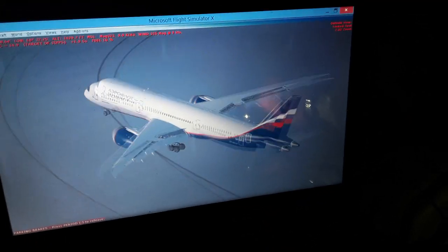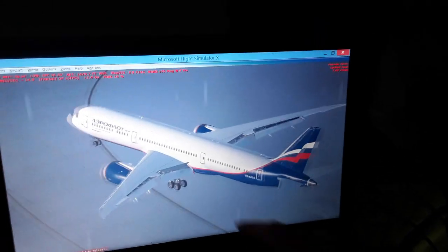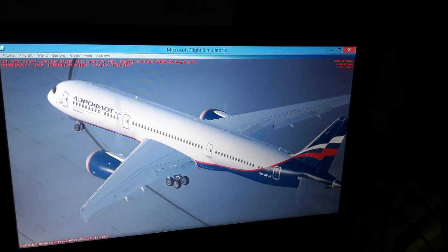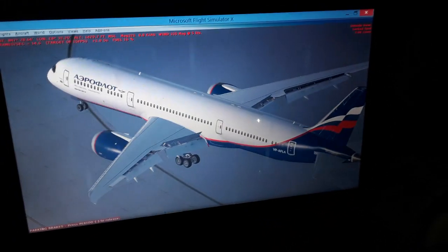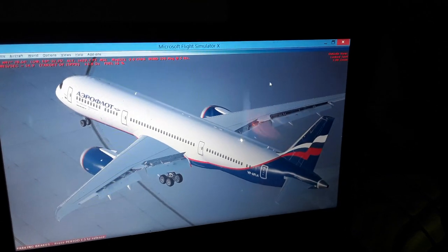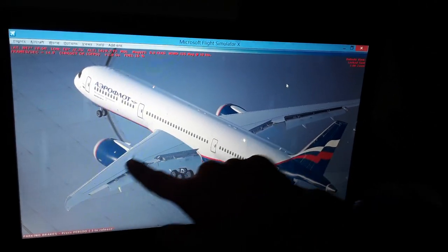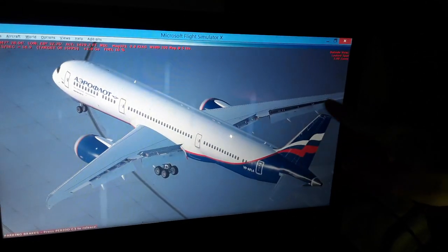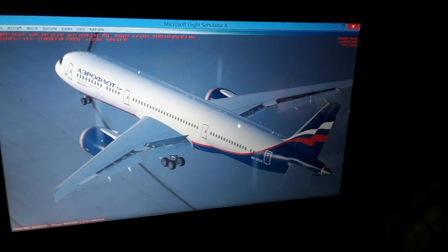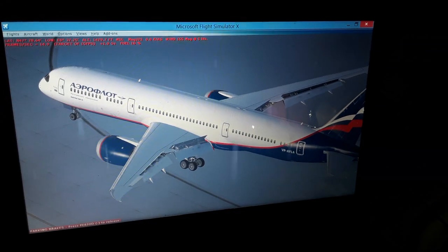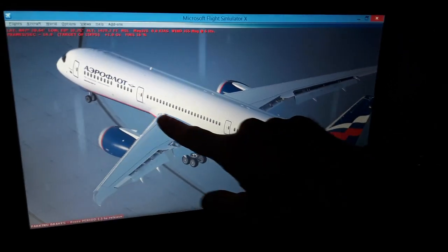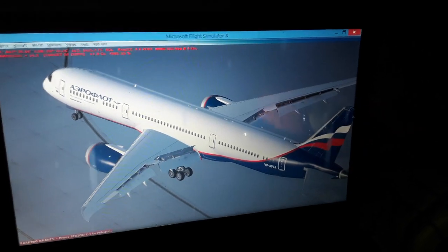So you can see here we have the aircraft, the Boeing 787. You can see the wings of the aircraft, and the weight of the aircraft as the aircraft flies. You can see we have the thrust vectors from the engines that move the aircraft forward. We have the mean aerodynamic chord position, the MAC, which is 23% of the mean aerodynamic chord. This is where the maximum aerodynamic lift appears in the wings, also where the stall usually begins for a given angle of attack in flight. The airflow becomes detached all the way back from here.